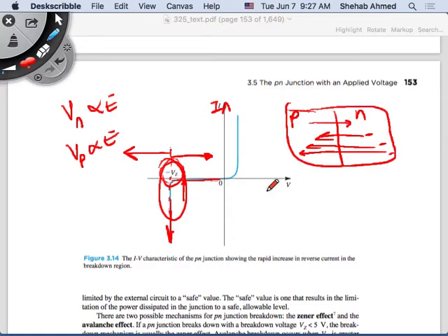We skimmed through the width of the depletion layer last time, but it depends on doping, on the way you dope the semiconductor material. So you can play with that such that you have control over Vz. You can make this Vz high or Vz low at the point beyond which this current starts accelerating to a very high value. Right? So again, around Vz, it's called Zener mode of operation or Zener breakdown.